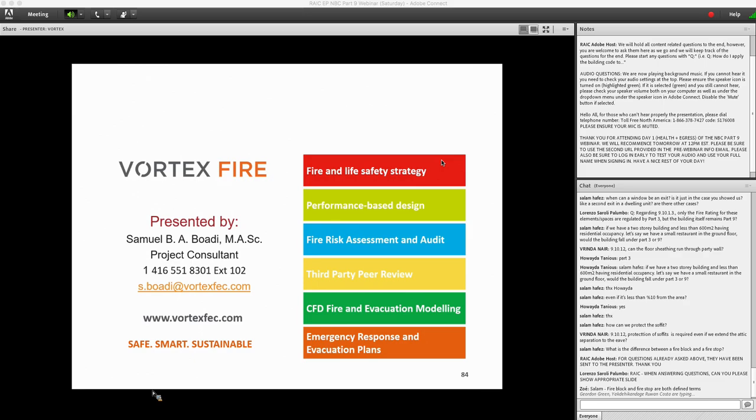There is a question on how about the doors to individual units. I believe this is related to the door swing. The door swing is typically not applicable to dwelling units containing a house or secondary suite. The swing is applicable where you have an occupant load of 60 or more, in which case it has to swing in the direction of exit travel.